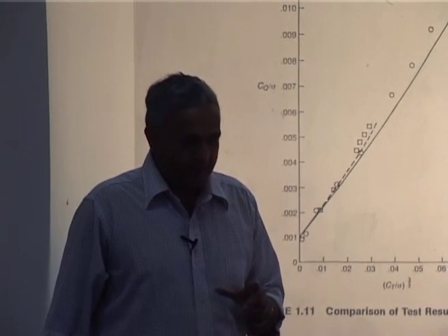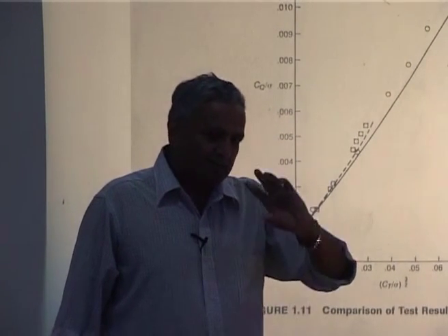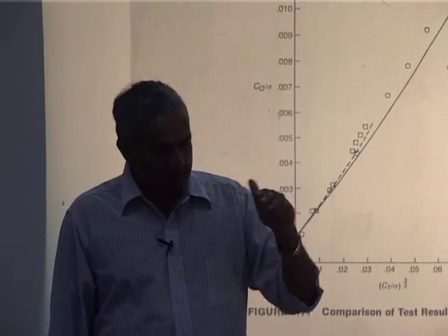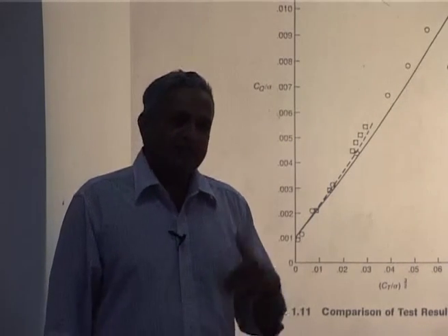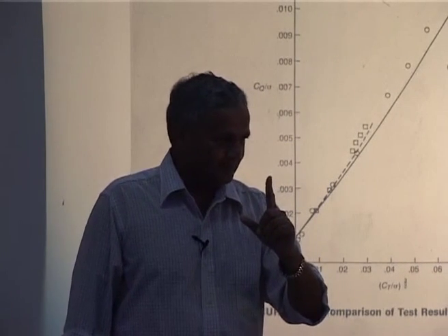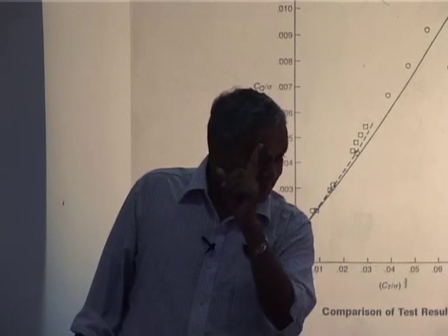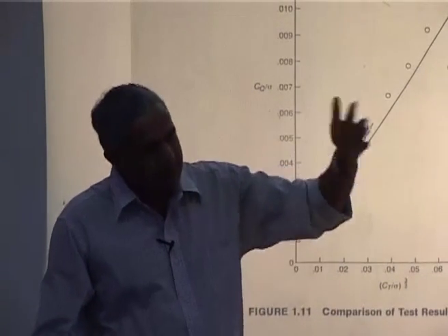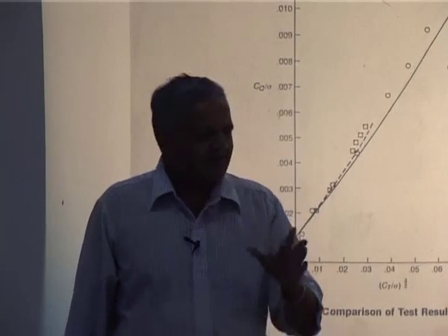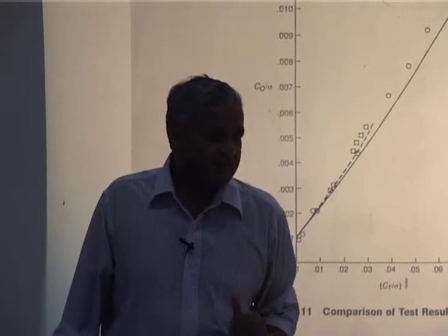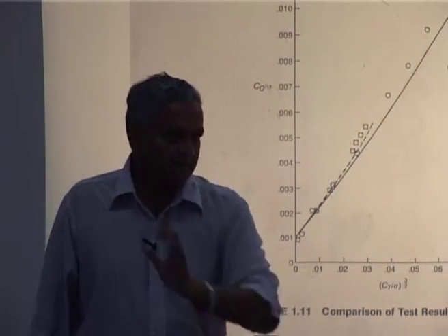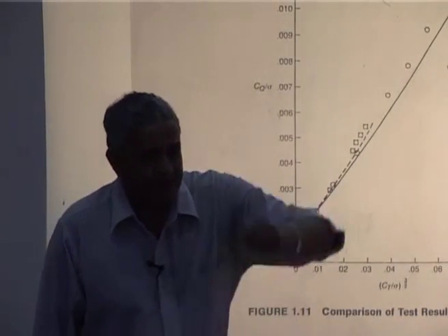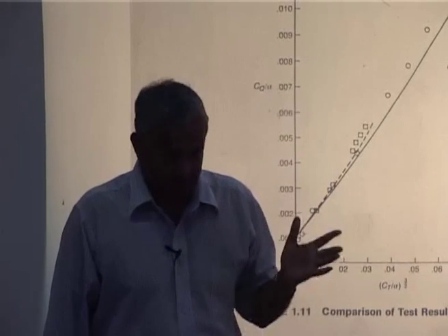Please understand. But Ct by sigma as a non-dimensional parameter is the blade loading, or indirectly the pitch angle. What is the capability of the rotor? How much Ct can I really take before the rotor becomes, one way is stall, another way is vibrating. There are several factors. Another one is that hub load increases. So you can set various criteria, and you take the rotor to the extreme.